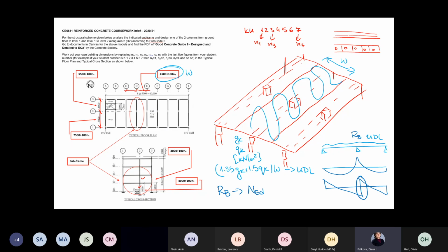Now, of course, at this point, you can say, well, can I use a different type of subframe? And the answer is yes, of course. However, because it has 3 joints to analyze, I think students are put off a little bit, but just be aware that this is the actual subframe that we usually analyze to find our moments in the beam and in the column elements as well, and shearing forces as well. So you have the option to do this. I'm discussing this in the lecture from last week. But if you want a slightly quicker analysis, the continuous beam with 2 spans is probably the safer option, the easier option.